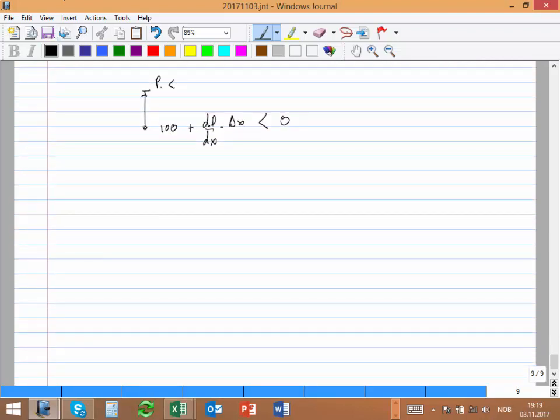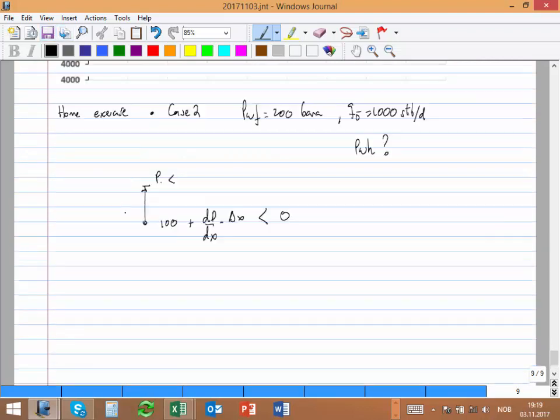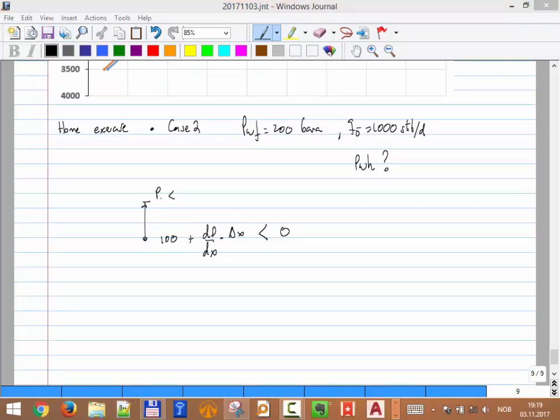With that, we conclude. So we talked in the first week about an overview of how the production system looks. We said you have different systems, but basically you all the time need to test the well. So you need a test separator and a production separator, and then you have routing valves that decide where to send it. And this sometimes causes a very big cost, especially for offshore.